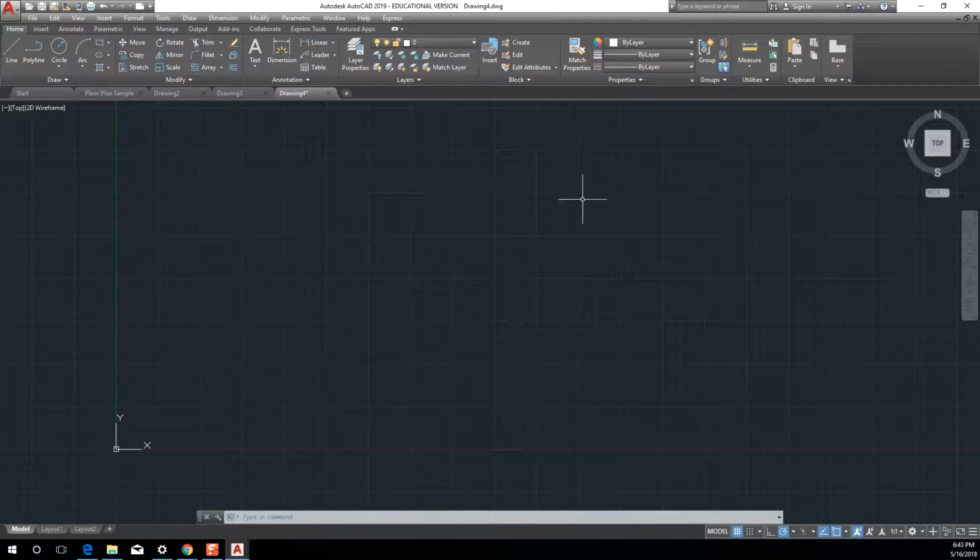All right, so we have model space, and in model space, whatever we're drawing, we draw it to real world scale. So our building is 10 foot by 60 foot. We draw it 10 foot by 60 foot in AutoCAD. Great. Okay, and we have an infinite drawing board, which means that we have plenty of space to draw all of these things and have them fit.